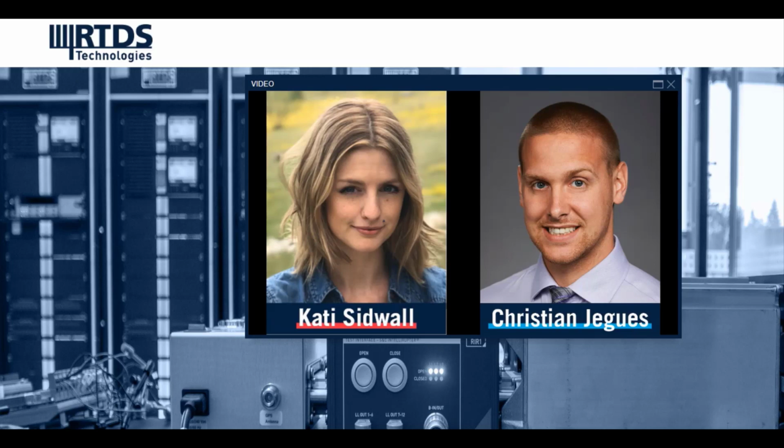We have a customer that's doing testing of about 20 different distributed controllers right now, so that kind of scaling is definitely possible. And that scaling comes through the actual processing hardware in terms of licensing more cores on the simulator, increasing the size of the system, and also in I/O. The I/O that Christian was using in this demo is on modular cards, and you can increase the number of channels that are available by connecting additional cards to the simulator. So the answer to that one is yes.